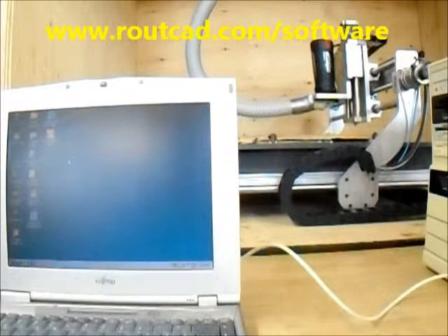Now the CNC controller PC that we are using only has one COM port, and by default it is COM 1. But if it had two COM ports, we have to make sure that we're connected to COM 1. If we connect to COM 2 by mistake, there will be no communication. All we have to do is swap the cable, connect to COM 1, and try re-establishing communication again.